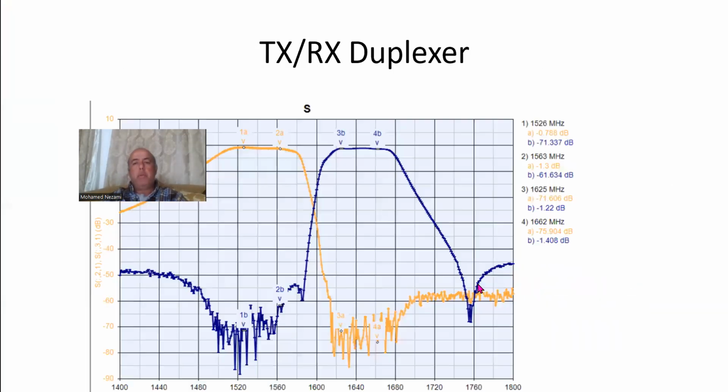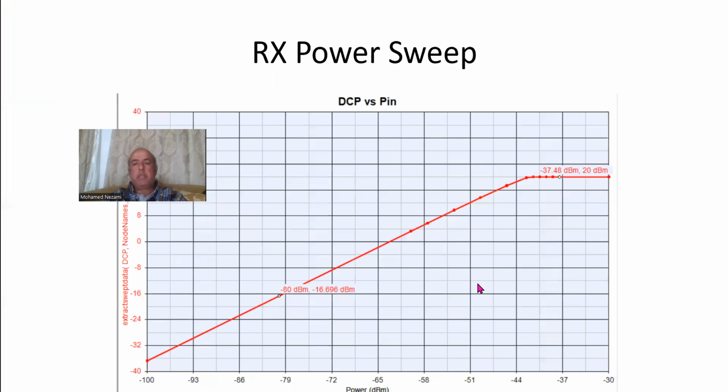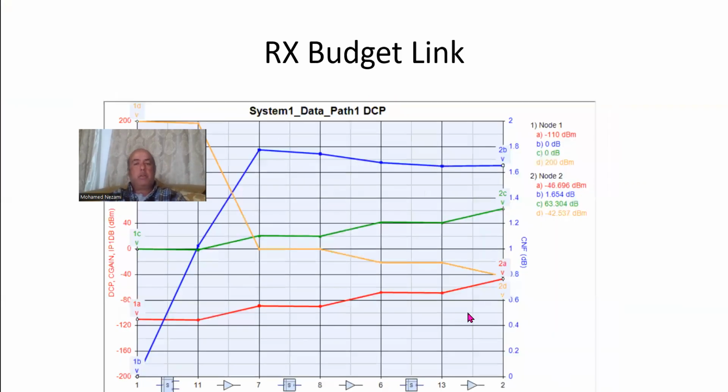Now, you might want to make sure that that 20 dBm is acceptable to the demodulator, because a lot of times with these demodulators, you don't want to damage or overdrive them. You're not going to get any SATCOM signal that will result in 20 dBm, but you might get an oscillation, or some kind of interference that leaks in the lab, and then it might be very easy to put you at 20 dBm at the demodulator. So make sure of that level. If not, then you need to possibly change this device.